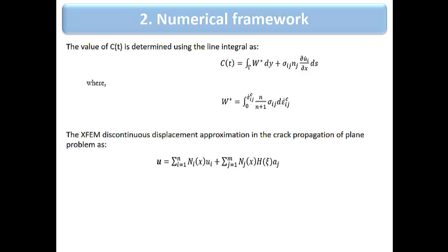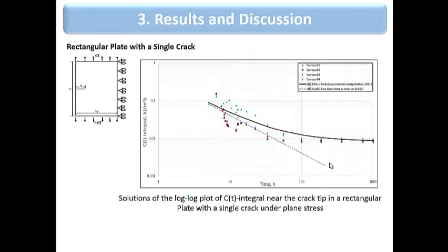Here, C(t) is calculated based on the value of the strain energy rate density, and XFEM is calculated based on the discontinuous displacement approximation on the crack propagation of a plane problem. Next we go to the results and discussion.